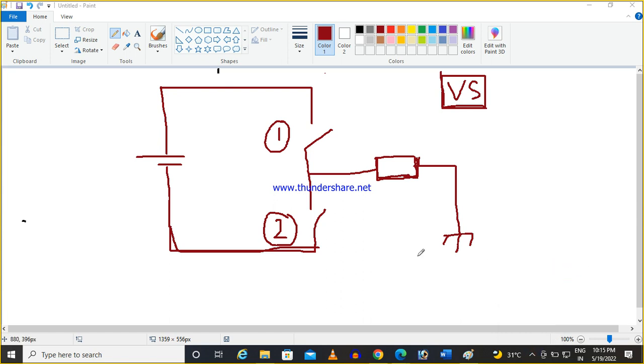Okay, so what I was telling, if at any instant these two switches are on together, the DC source will get shorted through this path, and a very high inrush current will flow, which may destroy the PN junction of these switches. So while you are designing the inverter and writing the code, it is to be taken care that at no instant should these two switches be on together.